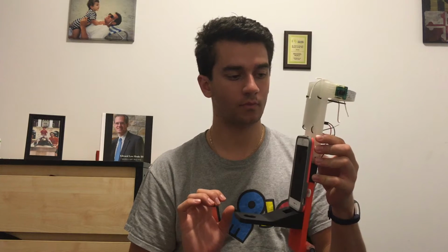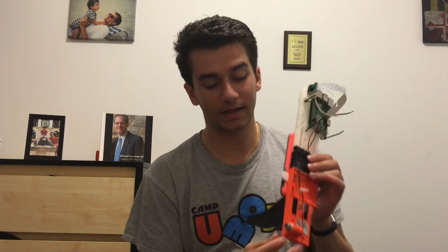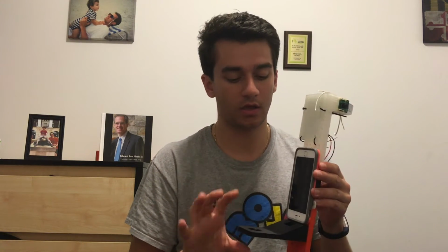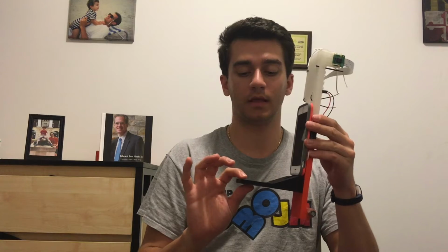In this setup, the red line laser here acts as the signal transmitter, and the Pi plus camera acts as the signal receiver. The phone command strip to the back provides angle of tilt, which is used during data collection, and the tripod attachment allows me to place the sensor on the tripod to get it to the correct height and have easy angle adjustment during data collection.